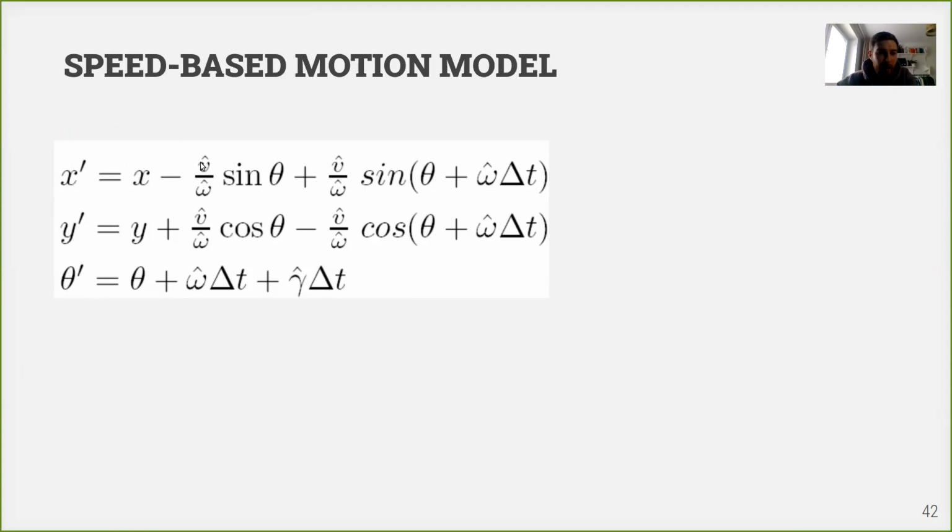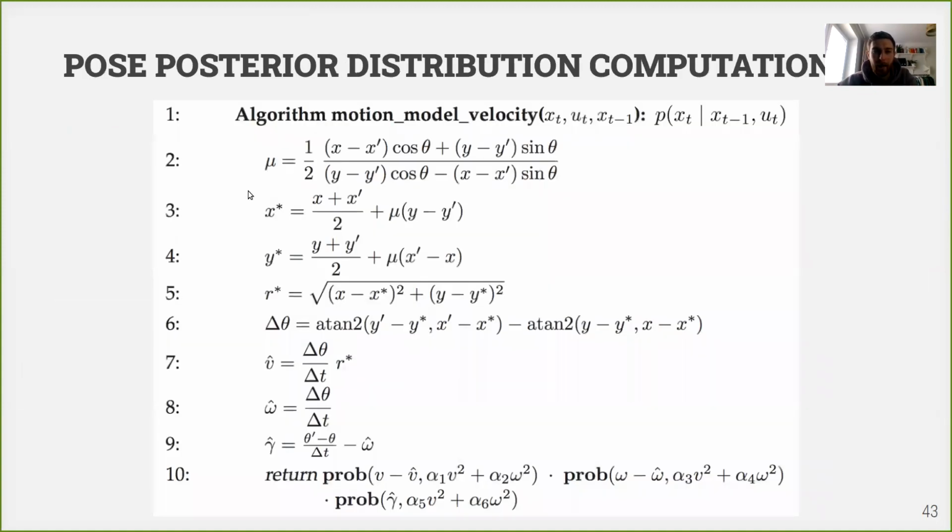And you can see here that instead of radius, which we had in the first part of the lecture, we now substitute radius with the fraction of linear and angular velocities, and that's how radius is computed. But since we are controlling these two parameters, we want them to show up in our equation. That's why we are substituting radius here by the division of these two.